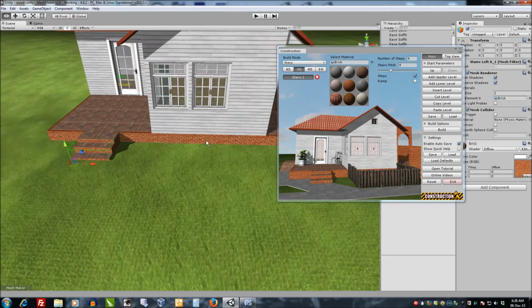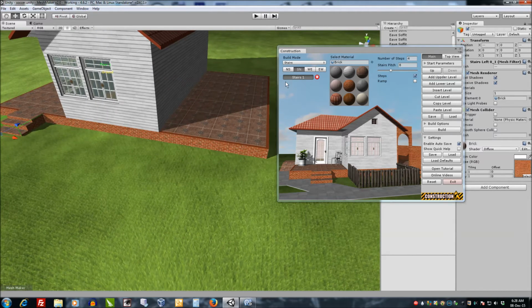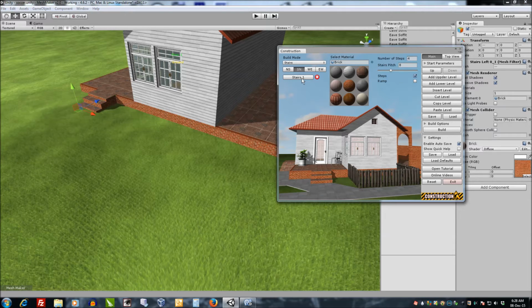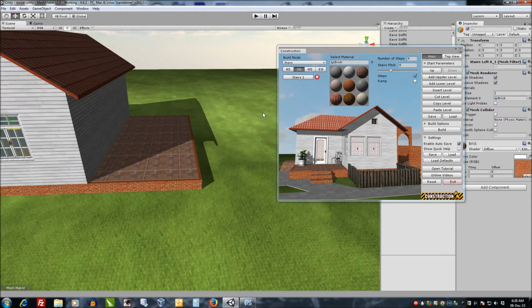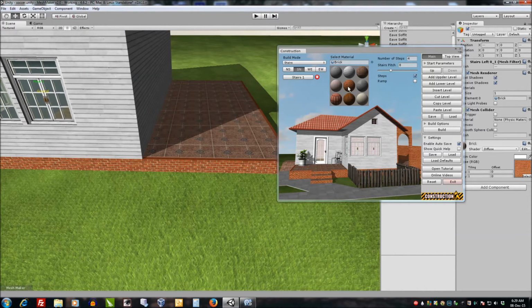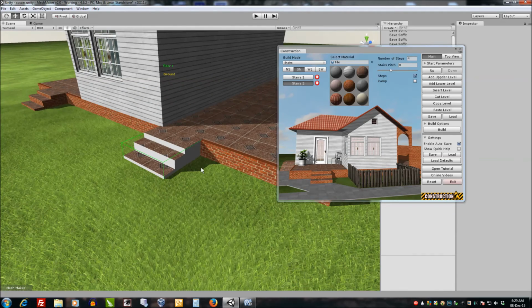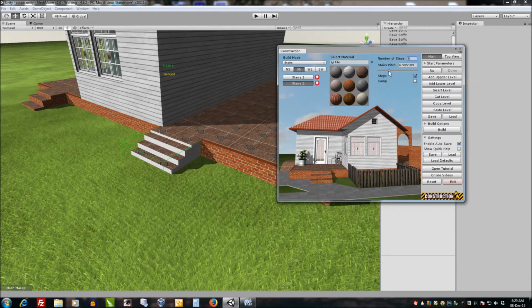The stairs that are selected have this green box around them. So after you've created some stairs, they become enabled or selected, and you can deselect them or select them using this interface here. And we'll just continue to add some stairs. And you can change the number of steps. It's currently selected, so we can change the number of steps to, let's say, 6, and change the pitch very easily just by moving the slider here.